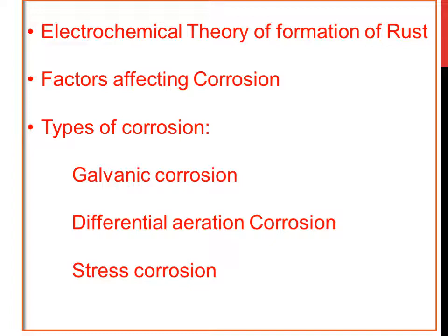And even the conductance of the medium: the rate of corrosion is more under wet or moisture conditions. The conducting ability is more, meaning the diffusion rate of the ions or electrons is also more. So the rate of corrosion also enhances. And even the temperature has a direct influence on the rate of corrosion. The rate of corrosion is directly proportional to temperature. One more fact is that as temperature increases, conductance of the medium also increases, so the rate of corrosion also increases.